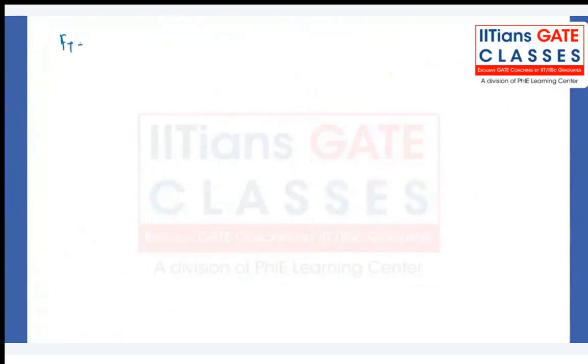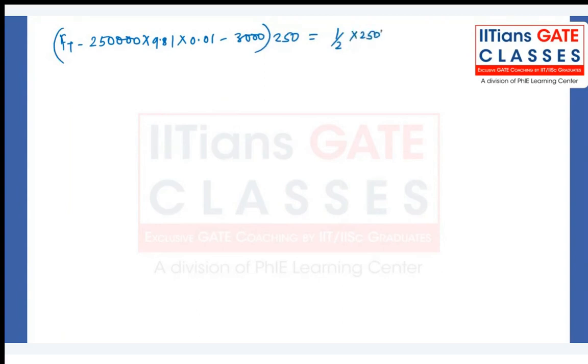Okay, so in this equation 1, if you put the values, you should be able to get the answer. So Ft minus, what is mg sin theta? It's 250 ton. So 250 into 1000 into 9.81 into sine of theta is 0.01, minus 30,000, that is frictional force, into 250 meters is the distance traveled, equals half of m, again mass is 250 into 1000, into 12.5 square minus 0 square. So this will give you the answer. Ft, tractive force, is around 132650 Newton.